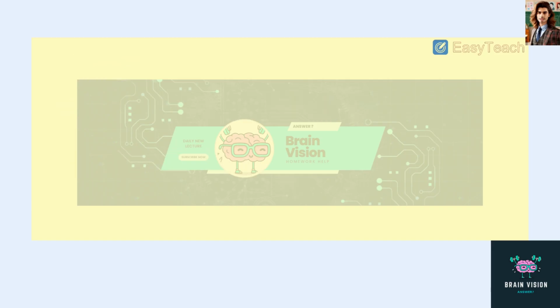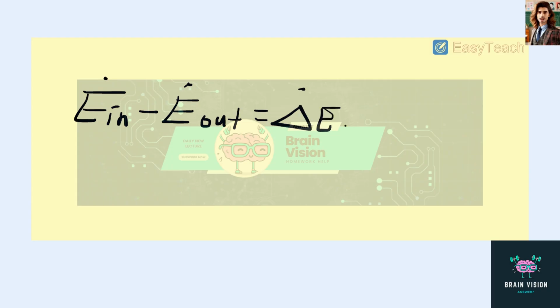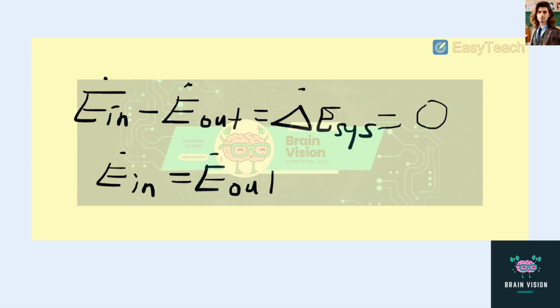So what we're going to do is actually define the system first, and we're going to define the system as the pipe. And when we do our energy balance, we see that the rate at which energy flows in minus the rate at which energy flows out is going to be equal to the rate of change of the energy of the system with respect to time. But since we know this is a steady state problem, this is going to be equal to 0. So therefore we have that the rate of energy coming in is equal to the rate of energy leaving.